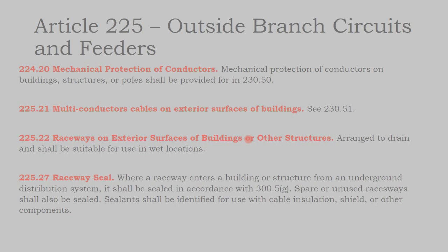So, in other words, you might have your wires coming out of your array into a box or into the roof itself. You might be going from a box into the roof. Well, you don't want to arrange your wires and conduit such that, let's say you put the box at the bottom of the rooftop instead of the top of the roof. If your entry point is at the bottom of the rooftop, it could be that the water is flowing down the roof and then it might run into the box.